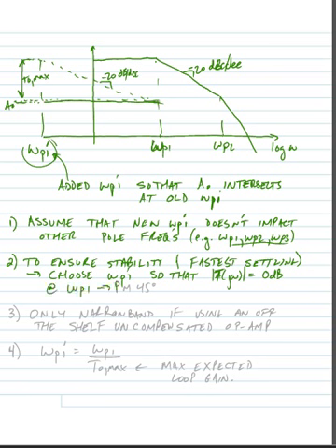And of course this yields a phase margin of 45 degrees. You could see that we would get a phase shift total of 90 degrees for this first pole, and at this second pole we'd have 45 degrees for a total of 135 degrees, which is 45 degrees away from 180.